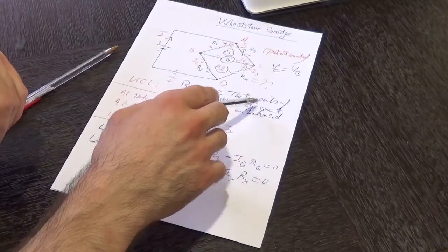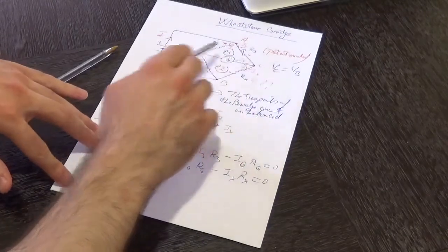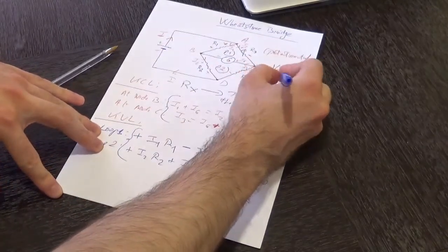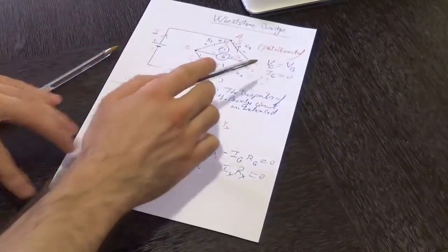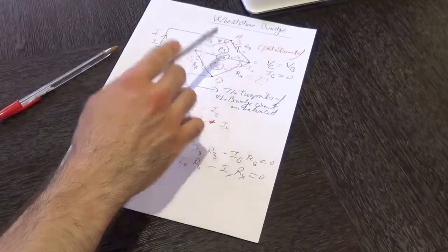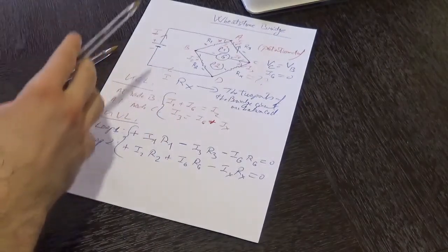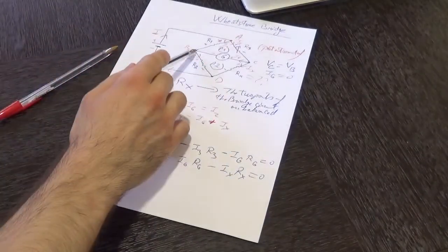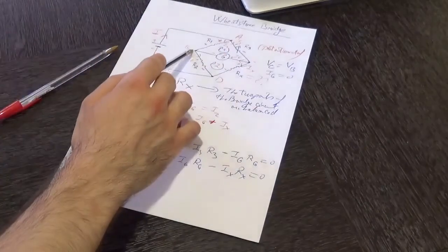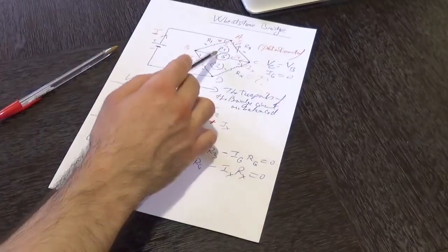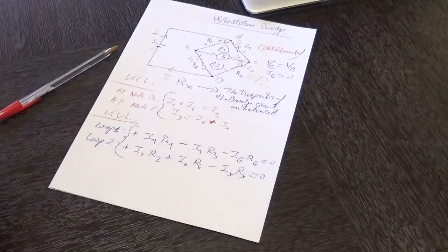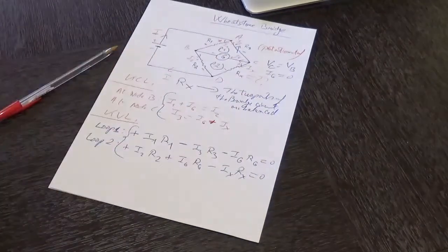So when these two bridges are balanced, not only Vc is equal to Vb, but also Ig is equal to 0. So the current flowing through that galvanometer is also equal to 0, because current always flows from a high potential point to a low potential point, and over here we don't have that condition anymore, but rather we have two balanced bridges, therefore we don't have any current flowing between them. So in that case, Ig would be equal to 0.